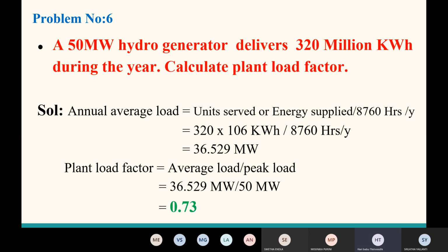That is equal to 36.529 megawatt. Now find out load factor. Plant load factor equals average load by peak load.